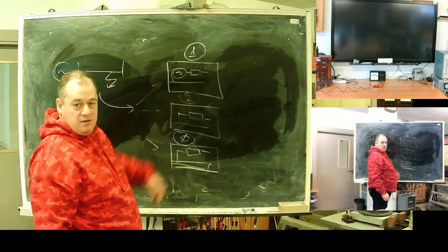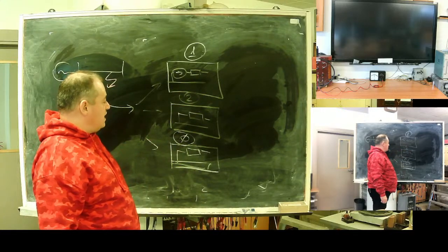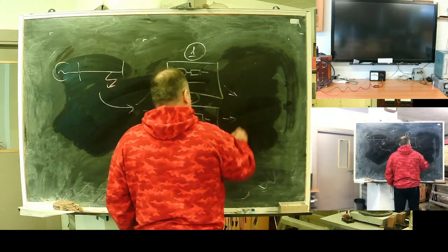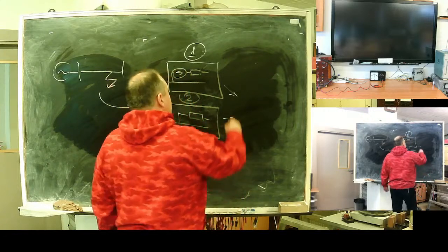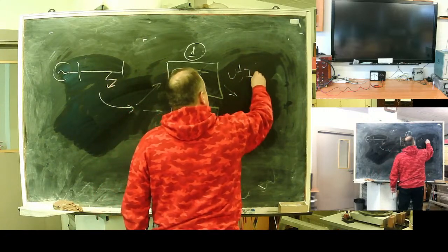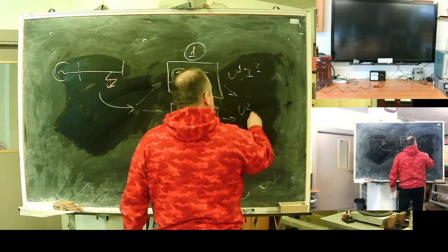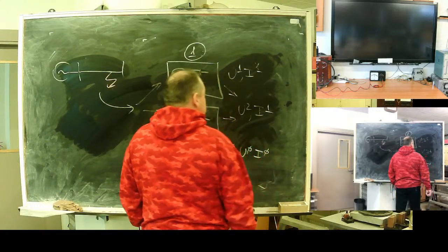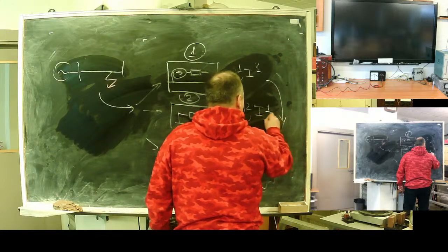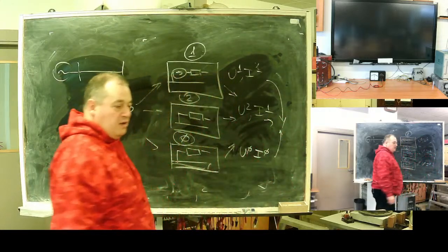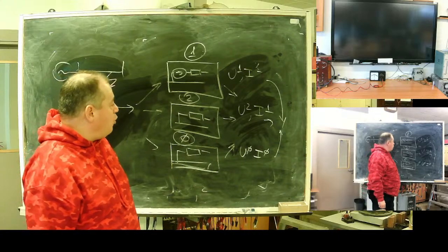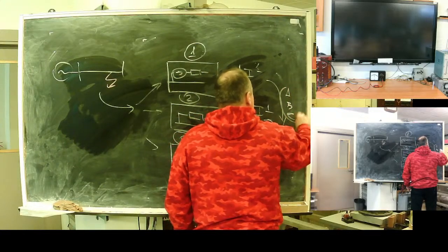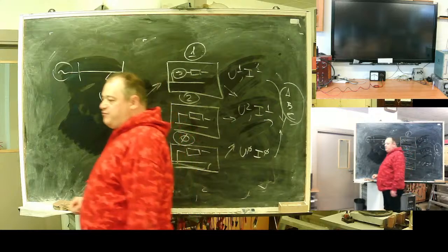They should be somehow interconnected or interlinked. Results will be current. We will get direct sequence voltage, direct sequence current, negative sequence voltage, negative sequence current, zero sequence voltage, zero sequence current. At the final stage we may want results as A, B, C, so we may need values in phase coordinates.